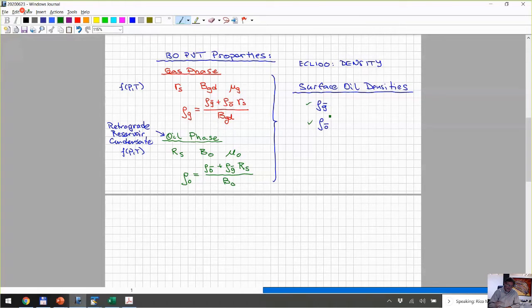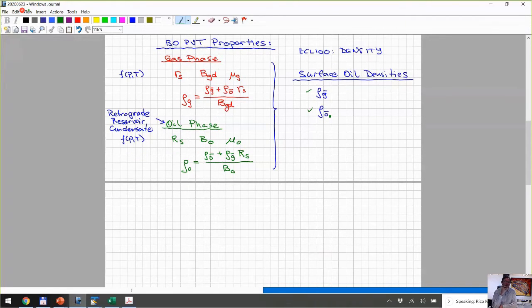Okay, thank you. The reason I asked is that when we did the explicit hydraulic fracture modeling, including the gridding, we really saw a condensate swamp, a highly saturated bottom part of the fracture with condensate, where it then also has mobility and can flow into the well. Our question was always whether this is realistic or some modeling artifact.